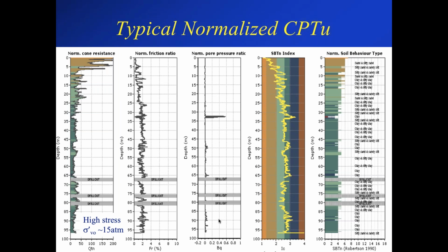The shear wave is where you would hit a horizontal beam. By hitting it horizontally, you're generating a shear wave, and that would travel down to the geophone in the cone. If you did that at one depth, that would give you the average shear wave velocity. But of course, if you repeat it every meter, then you actually get the interval velocity over that 1 meter.